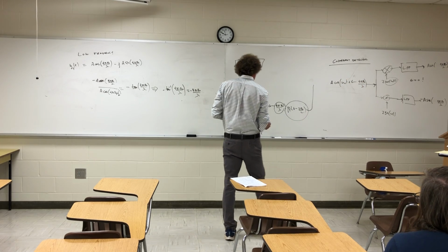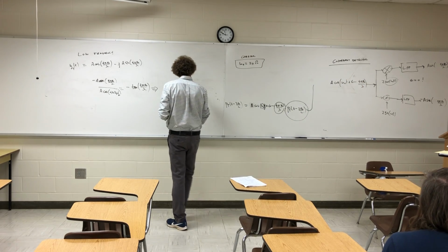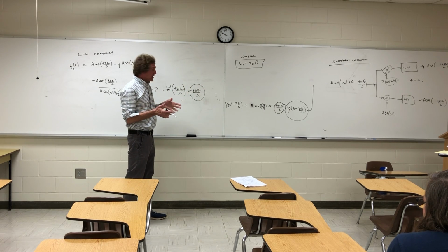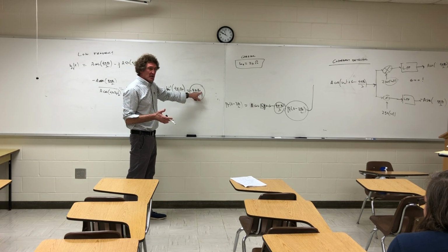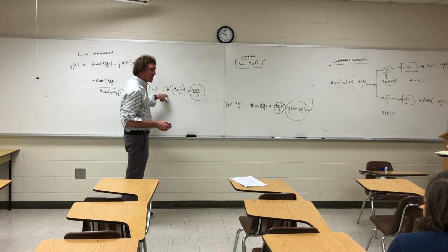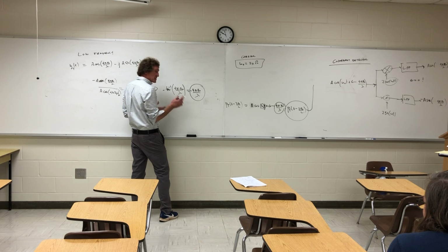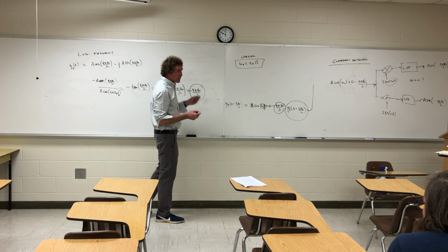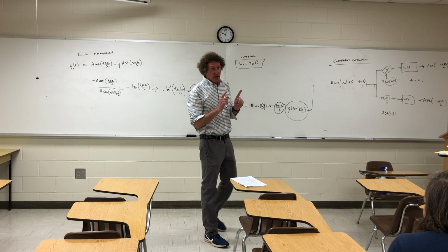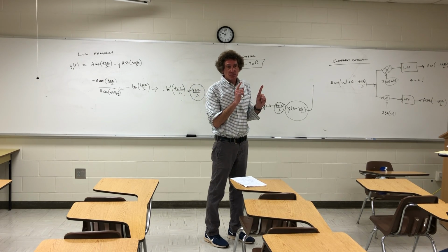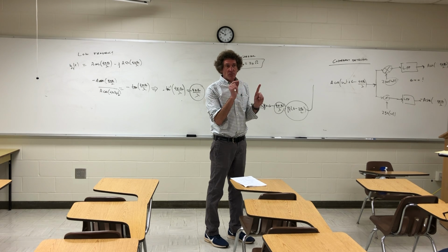Now we can get this bit of information precisely right here. And that will be a value. And look, we can get R naught. So if I take this, multiply by lambda naught, divide by 4 pi, I get R naught. Precisely. Y'all see what I'm saying? And that range, all of a sudden, is not limited by the range resolution. Remember, range resolution was equal to c tau over 2, right?